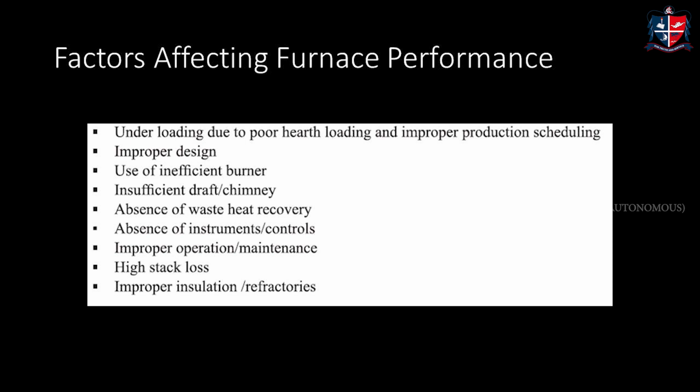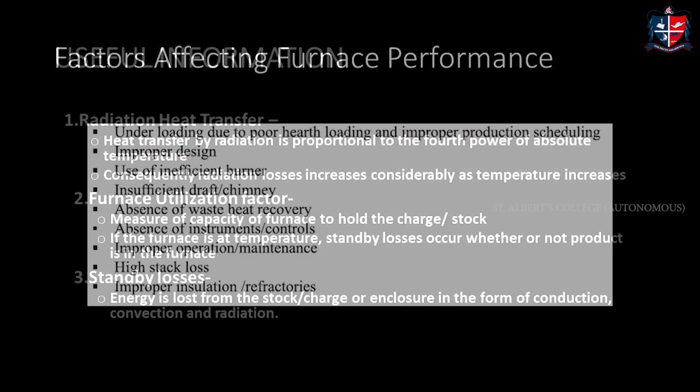We have improper operation. It has to be maintained annually or quarterly. Proper maintenance has to be done. Inefficient burners, fuel that is not of proper quality, or burners not of proper quality will also affect the performance.